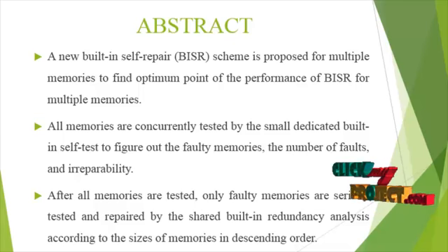In order to do so, a memory test is needed to identify the faulty regions. The memory is tested by external test hardware or by on-chip dedicated hardware, for example, memory BIST. The second testing strategy is the preferred method for embedded memories. After memory testing, the memory address map is programmed by means of volatile or non-volatile storage on or off chip. To provide the test pattern from a memory BIST, a multiplexer in front of the memory is widely used.